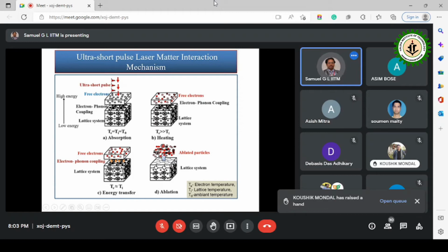But before that, these atoms or electrons and the plasma which is formed there just get evaporated. So when you use a femtosecond laser and cut a material, you can touch it immediately. But don't do that when you're using the CO2 lasers or the continuous lasers. If you touch that, it will be very, very hot. But with ultra short pulse laser, you can touch them immediately because there is no heat which has gone into the bulk of the material.